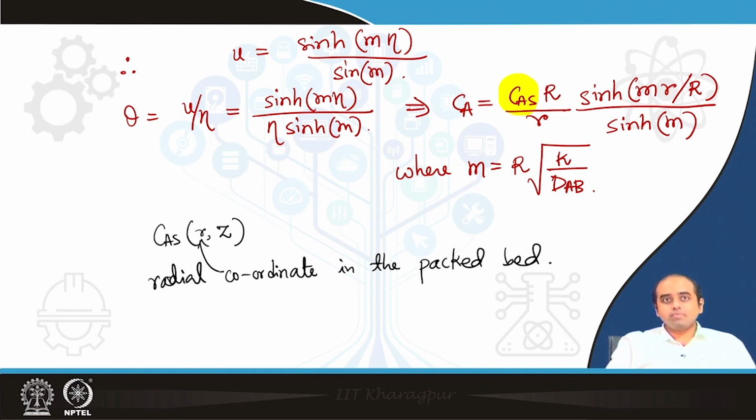Okay. So, simulating the packed bed reactor along with the particle level effects becomes a multi-scale problem, right, where at the bulk scale you solve the packed bed equations, but at the micro scale you solve the intraparticle concentration, and this is how these two are hooked up.